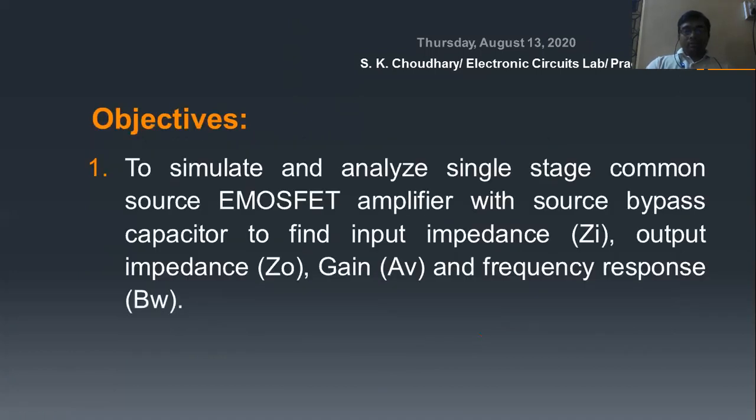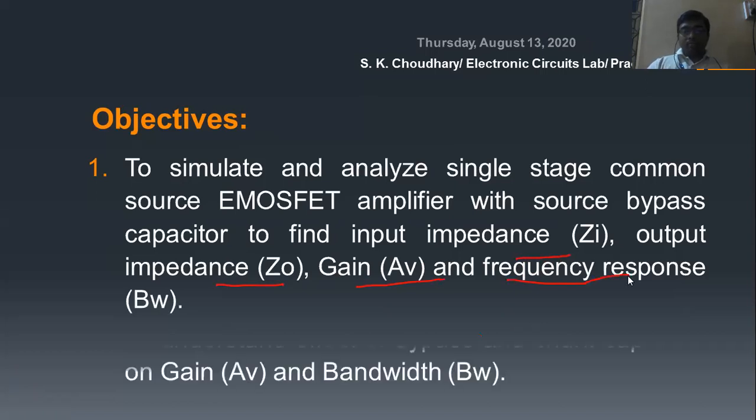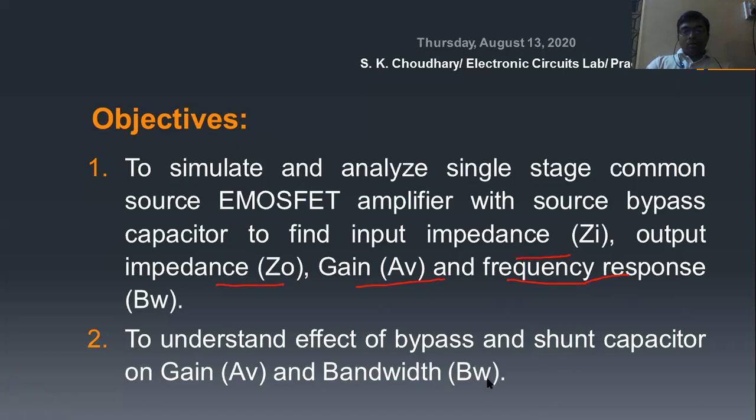We have calculated Zo, we have calculated the voltage gain, we have calculated Zi, and also we have observed the bandwidth. In this way, we have fulfilled all our objectives. So in this way we have simulated the common source amplifier with the help of Multisim.